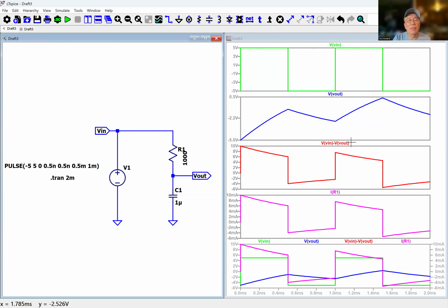So this tells you that if we increase the resistor R value or the capacitor C, the charging curve stretches out. If we decrease, the capacitor charges more quickly. If the numbers go down, the charge speed goes up.